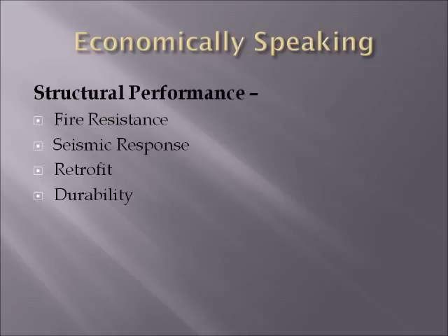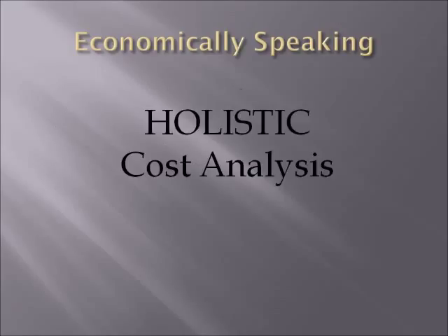In structural performance, the design engineer will find economy in structural lightweight concrete's performance in fire resistance, seismic response, retrofit flexibility, and superior concrete durability. When looking at economy of design, a holistic cost analysis process should always be used. Though structural lightweight concrete may carry a 25 to sometimes as high as 75% cost premium over normal weight concrete, the overall savings to the whole project in design will far outweigh these costs.